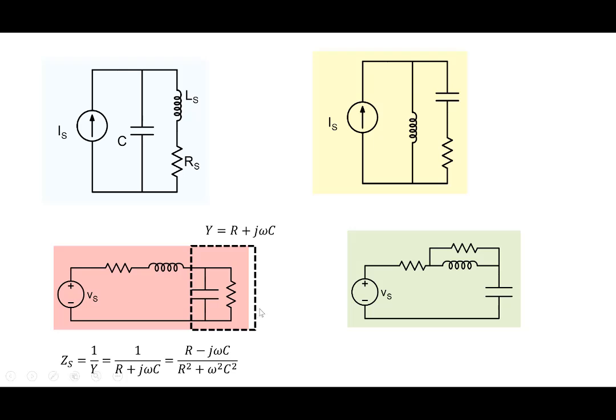Especially the zero phase or unity power factor frequencies become easier to calculate because that's the place where the reactance or the imaginary terms go to zero. The reactances cancel each other and imaginary terms go to zero here. So let's stop by saying that the concept of resonance, the phenomenon of resonance, allows us to build highly selective filters in a very efficient manner.